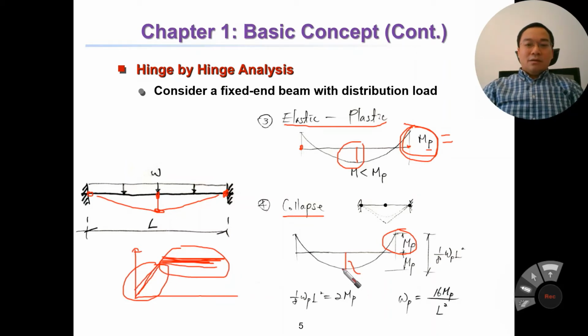As the load increases, the moment at the middle section increases until Mp. Now we have Mp here and Mp here, then we have 2 Mp.